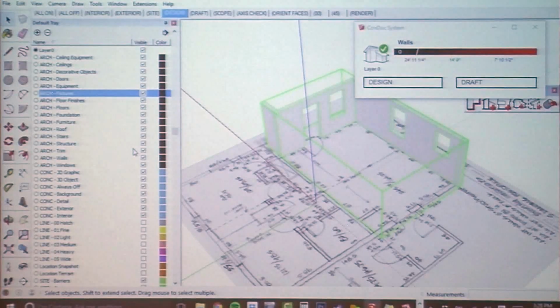And then we have something a little more descriptive, and those are conceptual layers. Those are the prefix CONC. Conceptual layers are descriptors. They describe the nouns or the architectural layers. So for instance, we have conceptual interior, conceptual exterior, conceptual level 1, 2, 3, conceptual new and existing. So this is how we can describe all of these pieces that go into our model.